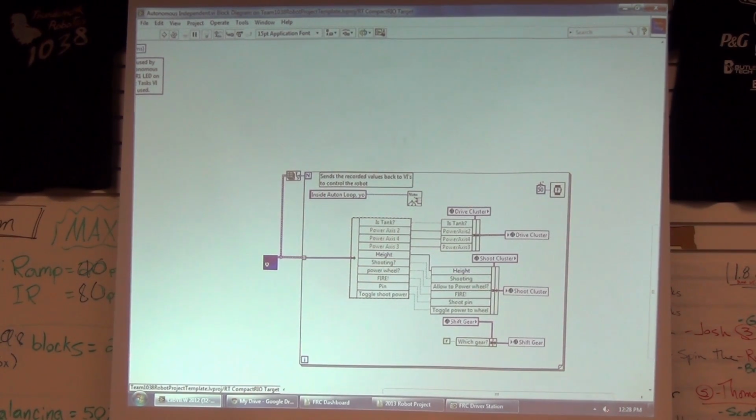So for driving in years past, we've used the gyro to say, okay, turn to this angle, and then drive straight. We do sort of not a PID, but just a P loop to say, okay, drive and stay at 0 so that we can drive straight in our time, something like that.